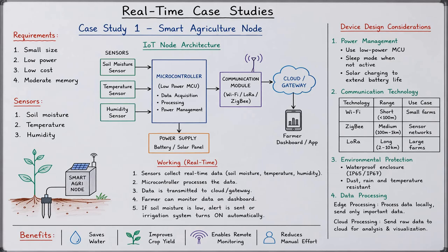So here the device design consideration which are considered for this case study are power management, where we use here low power MCU. It goes into the sleep mode when it is not active, and here we use the solar charging in order to extend the battery life.